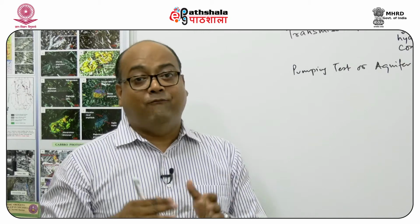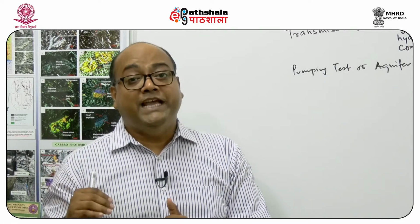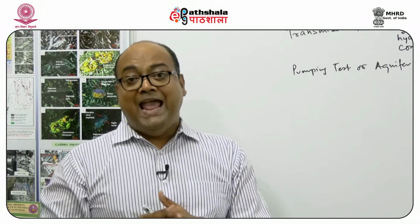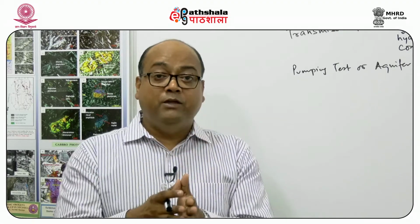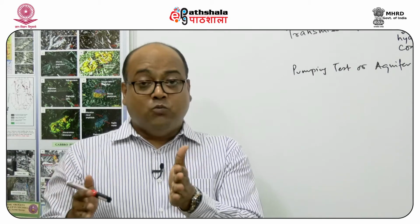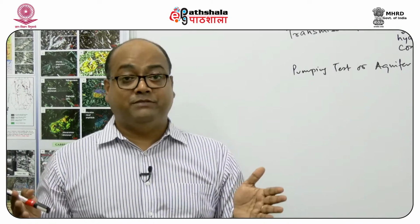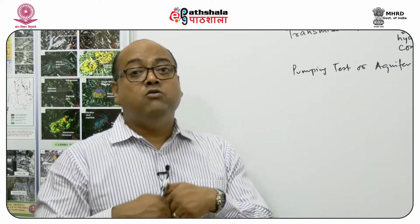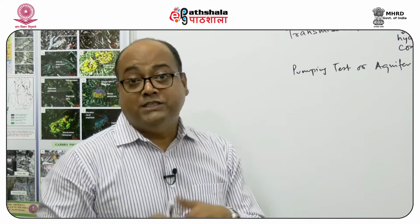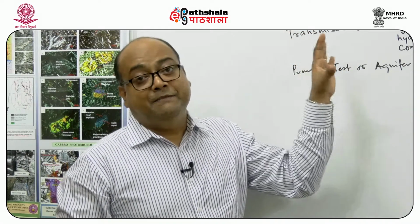For example, if I have one pumping well and another observation well, in this observation well we measure how much the drawdown is changing with time. In some cases we have one pumping well and several observation wells located at finite distances from the pumping well, so the drawdown is measured at all these different wells at the very same time. We'll see how these measurements of drawdown, varying either with time or with distance, are used to get these important properties.